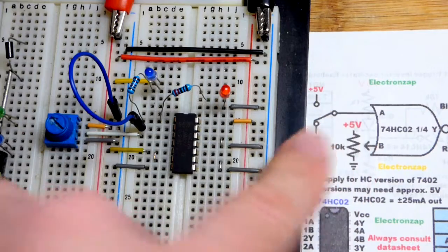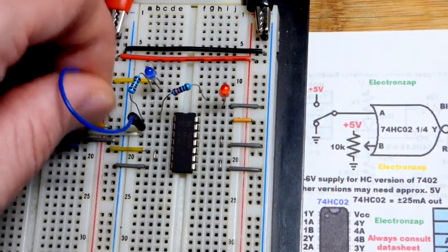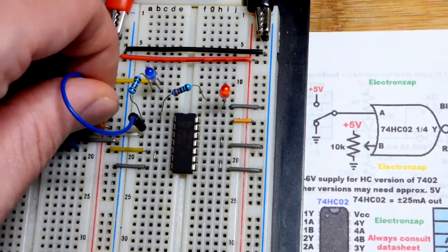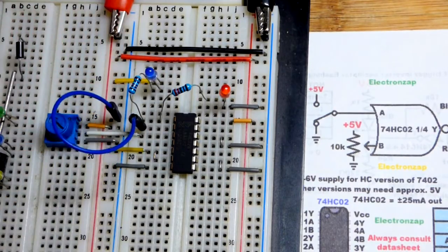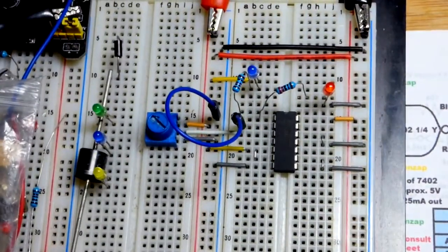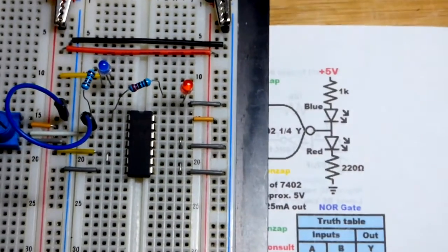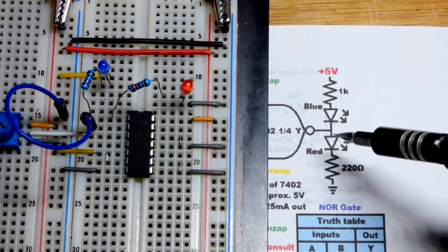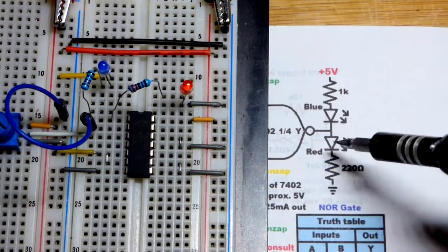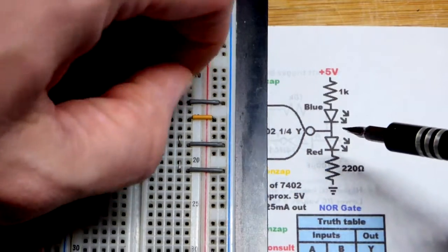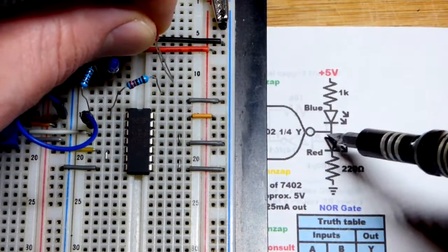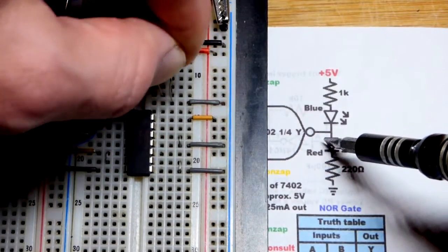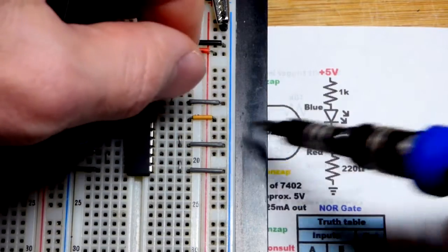I have a jumper, as I said before. I can move it back and forth between the two supply rails to give 5 volts or 0 volts for a more distinct voltage there. Then we have the LEDs at the output. As I mentioned before, I swapped the position of the resistor and LEDs, but they're in series, so it doesn't matter which comes first as long as the LED is in the right direction. So output, 220 ohm resistor, long lead, the anode, right there, that part of the triangle, to the resistor. Short lead, the cathode, is going to ground right down there.